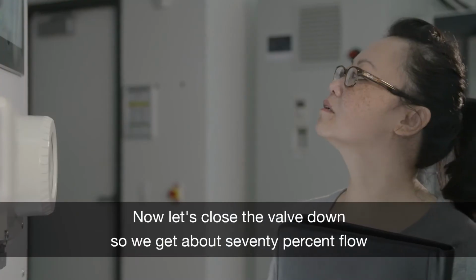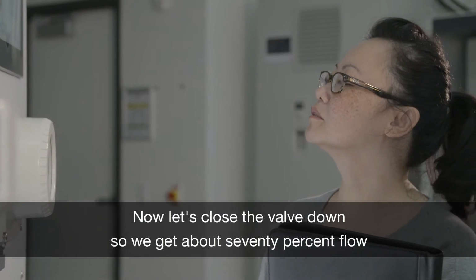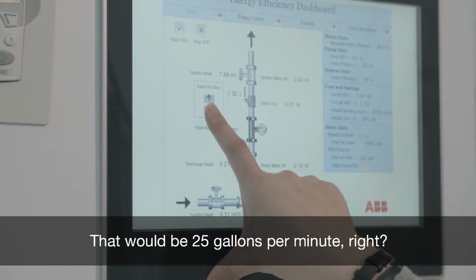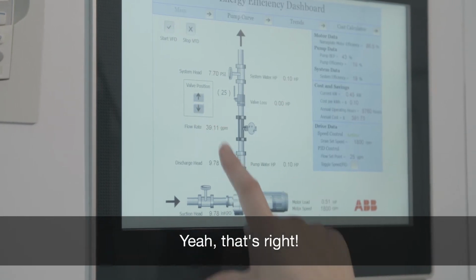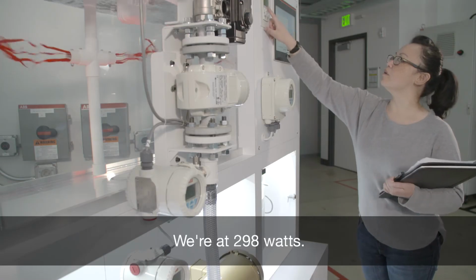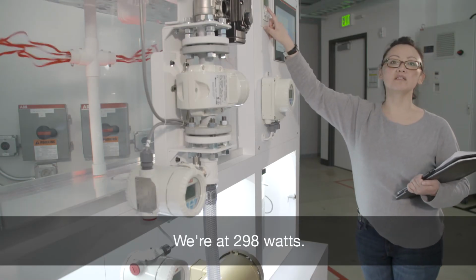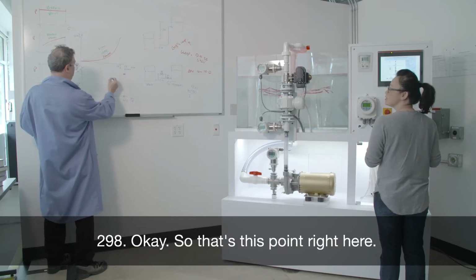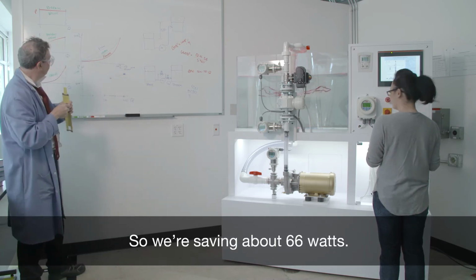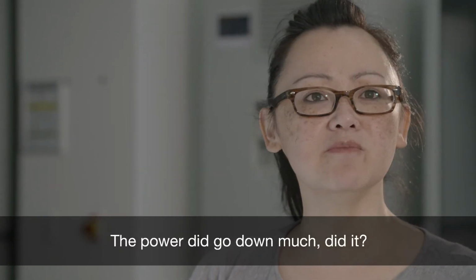Now let's close the valve down so we get about 70% flow. So 70% of 39 would be about 25 gallons per minute, right? Yeah, that's right. So with 25, now what's the power? We're at 298 watts. Okay, so that's this point right here. So we're saving about 66 watts. The power didn't go down much, did it?